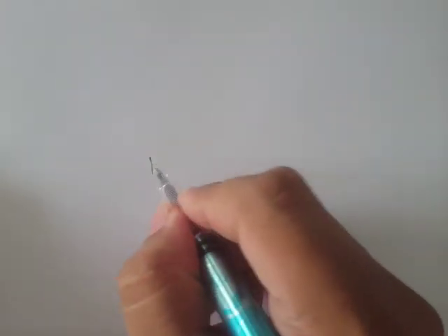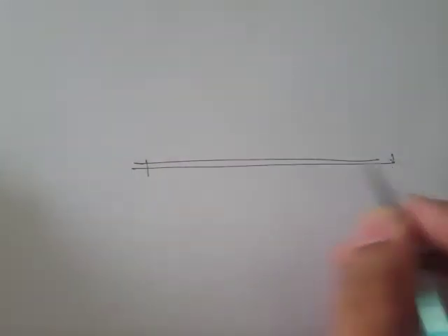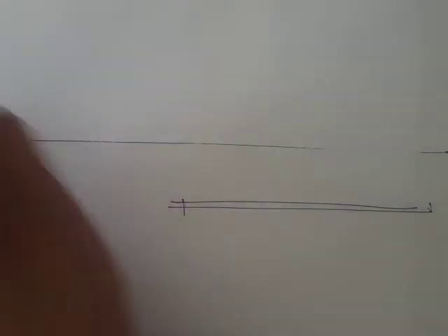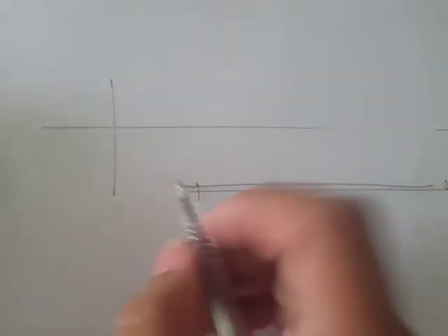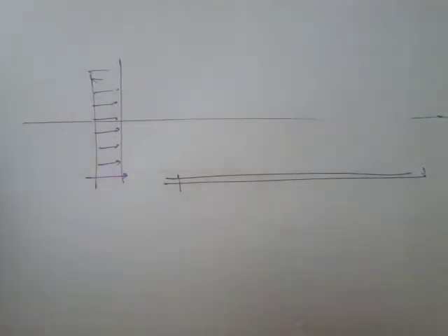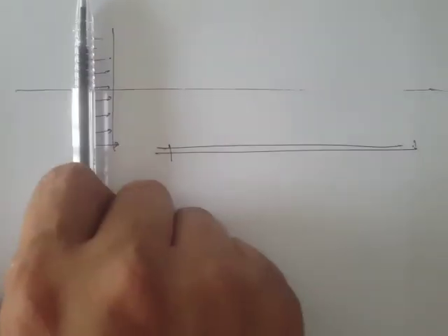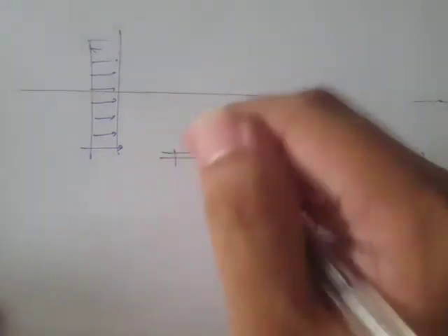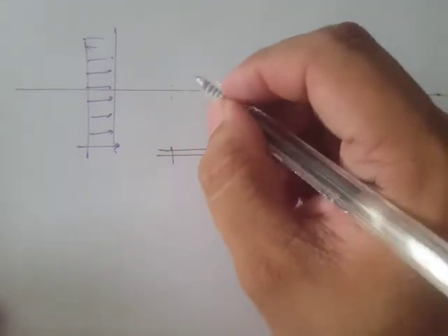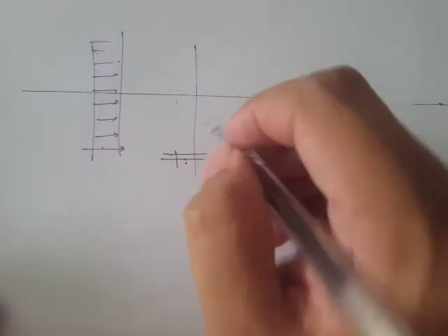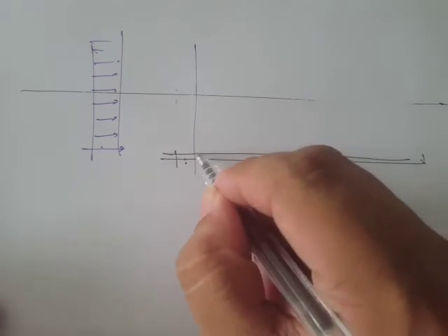let's just draw right here. So for example, we have a flat plate, and there's a fluid moving over the flat plate. Now, if we take the velocity profile before the flat plate, or before the existence of the solid boundary, then we have a uniform profile. However, as the fluid starts to move and touches the solid surface, the fluid adjacent to the surface would stick to the surface, so it will not move.